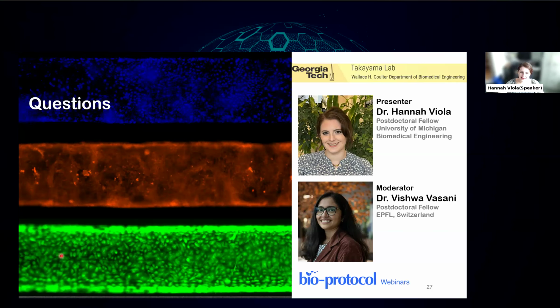We'd love to know, but I have a sense it would be pretty difficult, because if your PDMS is very stiff, like you said, it's going to crack, and you might not even be able to plasma oxidize it if you don't have any free moieties. And if it's flexible and not overly cross-linked, it's too flexible and you're not going to get clean cuts. You're probably going to get some breakage of the PDMS. So you want a stiff material that will hold its shape that you can cut into, like metal, wood, plastic, the ones we always mention.